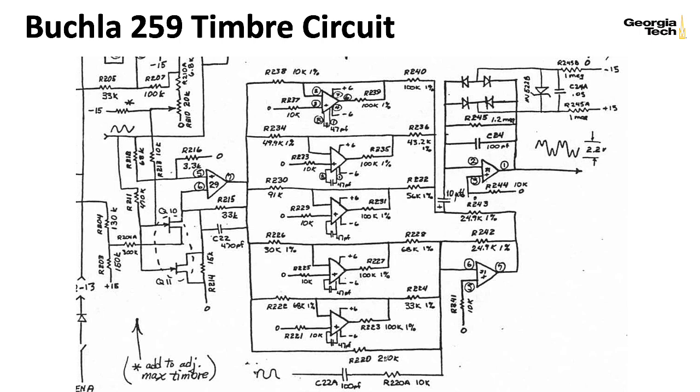Let's take a look at one of these. Welcome to Buchla land. Here we have the main input that feeds a bunch of these nonlinearities. One thing that's a little bit confusing is all of these 10K resistors to this 0. That 0 represents ground. And here those resistors are designed to deal with non-ideal op-amp effects. They don't really play an important role in our analysis, so we can ignore them. Just imagine that all of the positive terminals here are hooked to ground.